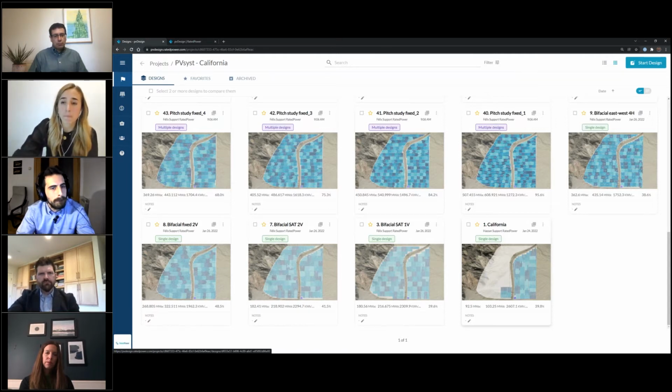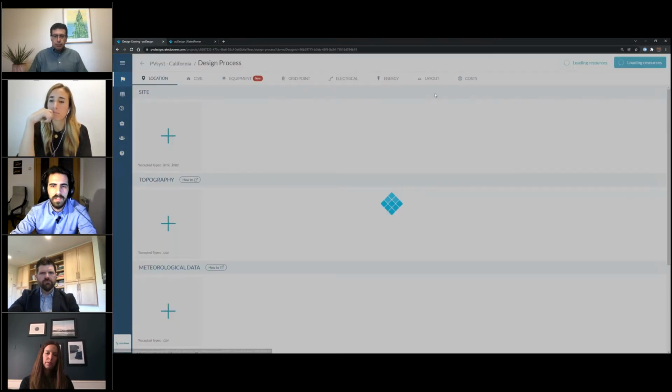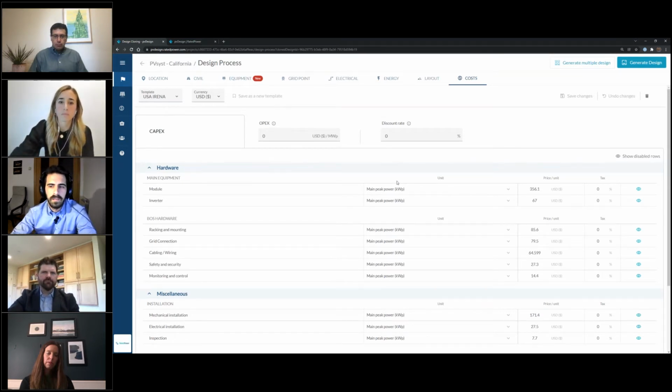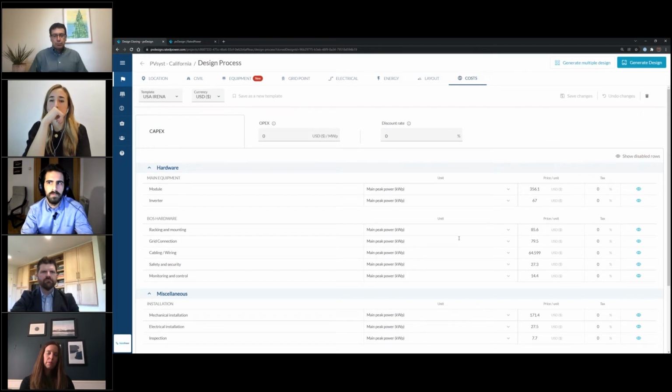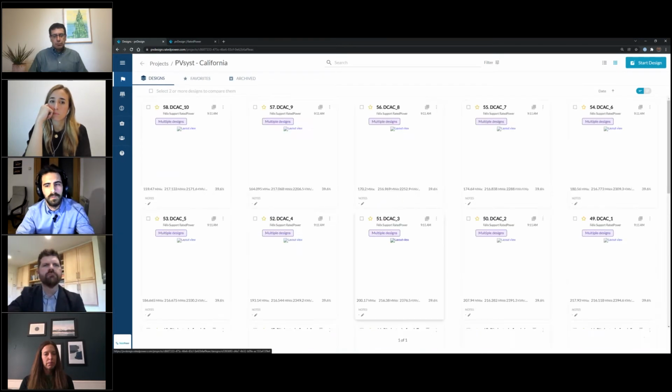And yeah. No, go ahead. And yeah, so the other thing I wanted to mention is that when we run these PVDesign simulations, we also can include the possibility of calculating the economical analysis as well. So you can do that really easily. You have templates which you can use to calculate the prices. And the thing is that when you incorporate this information into the simulation, now you're not only looking at layout and energy yield from an engineering standpoint, so megawatts peak in the PV plant, performance ratio and specific production, but you can also start looking at LCOE and the economic performance of the site. So it kind of ties together really nicely.